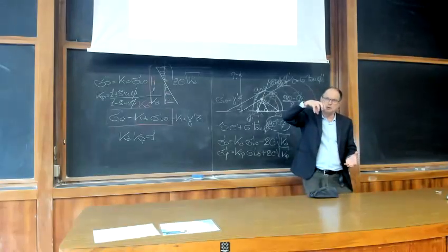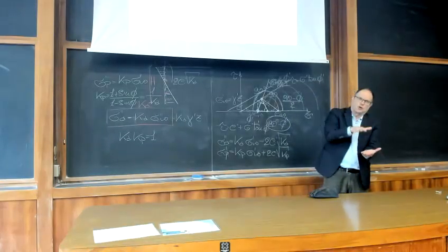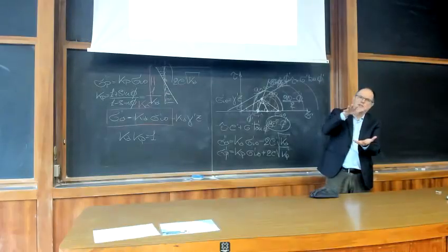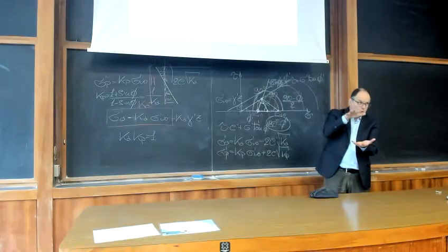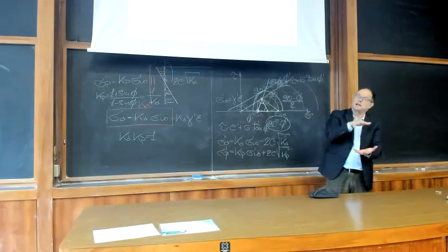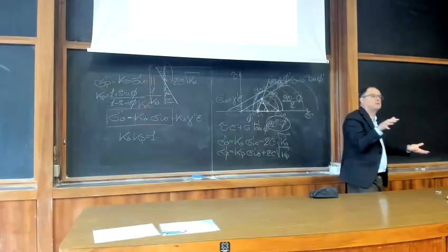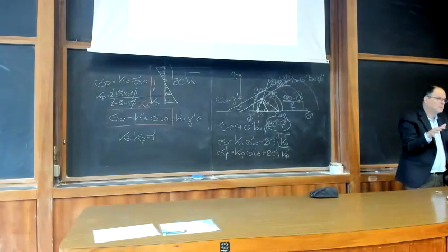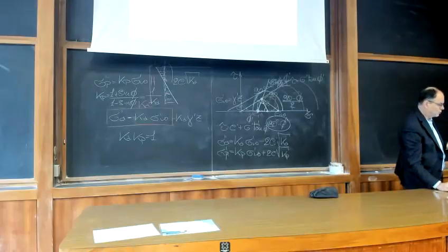So you have your foundation and you increase the load. You increase the load, you increase the load, and of course the soil below your foundation will tend to settle, to move down because of the applied load, unless the soil is perfectly rigid, and it is never perfectly rigid. Okay, so you have this trend. You increase your load, you increase your settlement.